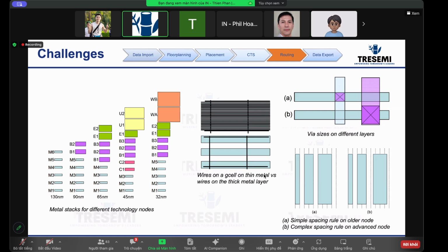Okay. And Bach, it looks like we've got a question, right along this idea of 2 dimensions versus 3 and the shapes of the wires. Wenhan Hai asked, in one layer, can we change the thickness of metal? No, so as you go from metal 1, the thickness of the layers is already fixed. You look at the 32 nanometers, right? Metal 1, 2, and 3, all those layers, the thickness is fixed. You cannot change the thickness of the metal.